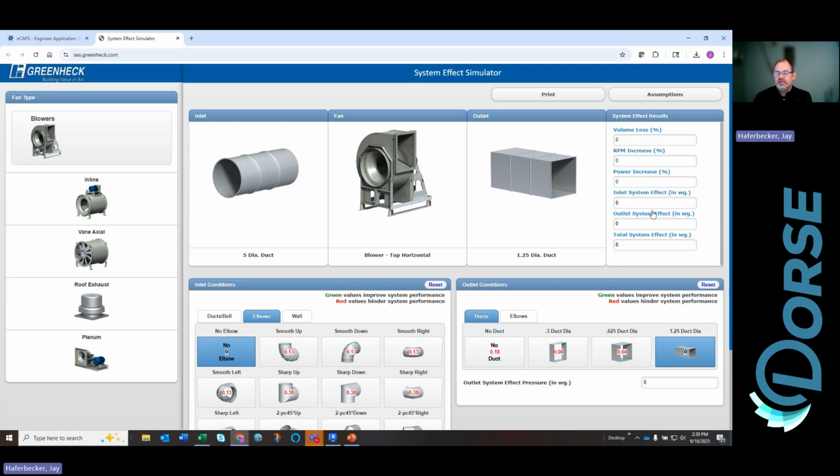Now, how many of you have seen blowers out on the roof, for example, in that upblast configuration, just upblasting directly without any ductwork on it? Those fans are probably losing 10% efficiency because they don't have a little short stack on that outlet, right? So that's kind of something interesting.